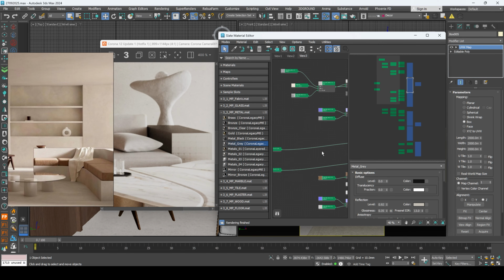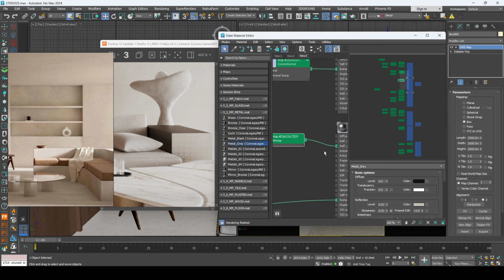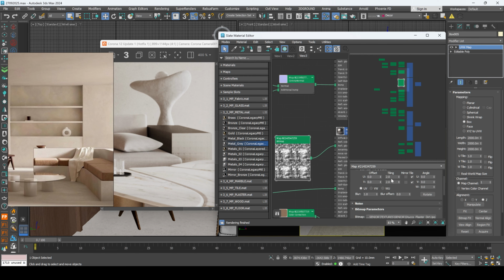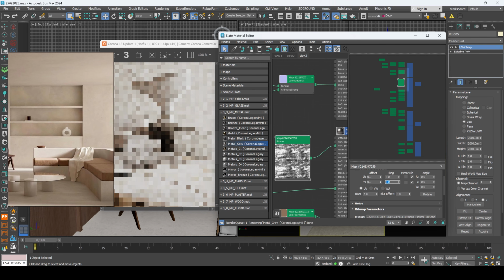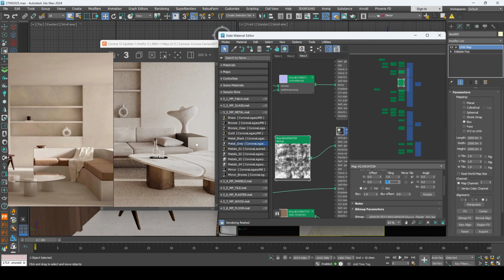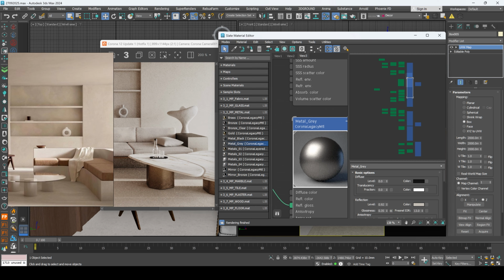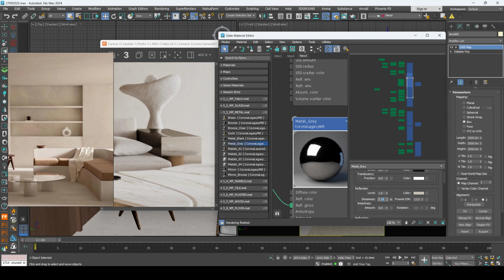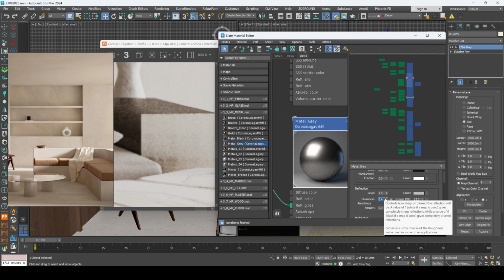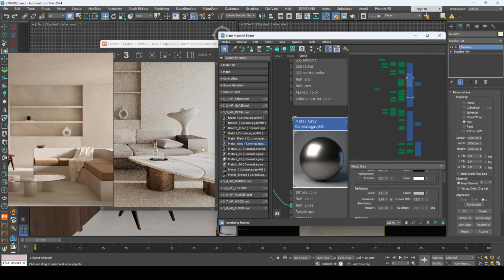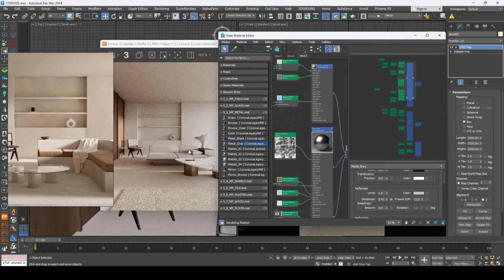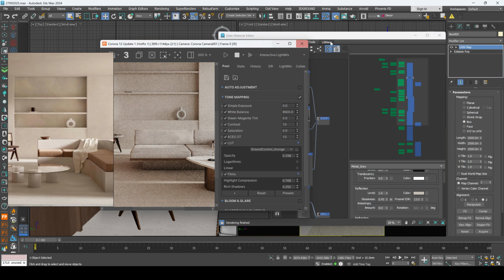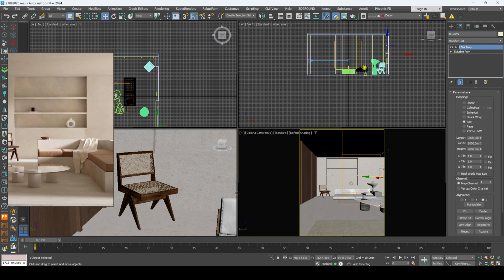Yeah, there's not so much roughness and reflection glossiness. So now let's adjust the map size right here. Let's click on 1 and 1 right here. Yeah, now it looks more accurate. And right here, let's add more reflection and glossiness. Not so much. Let's make it 0.4 or 45, I think. Yeah, now it looks pretty. And actually right here, the bottom side, it also needs to be adjusted. Yeah, so select this bottom side right here. Now I got it.